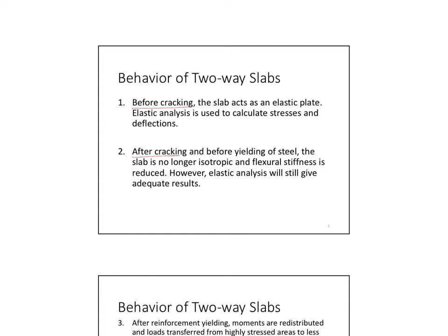After cracking, which most probably will happen at locations of highest moments, and for this we're most probably talking about edges and mid-spans. So edges would be the highest negative moments, and then mid-spans would be the highest positive moment. So those are the main three locations where we could possibly see cracking happening. And so those cracking